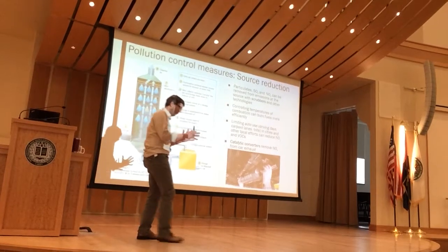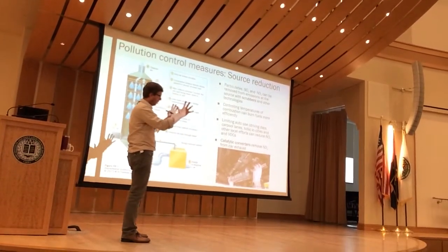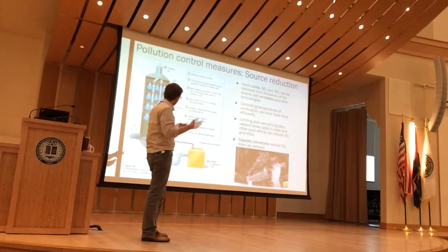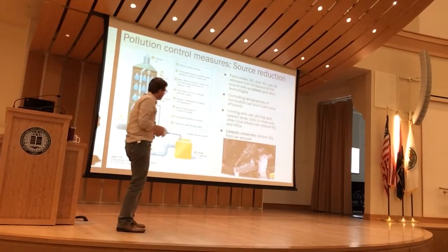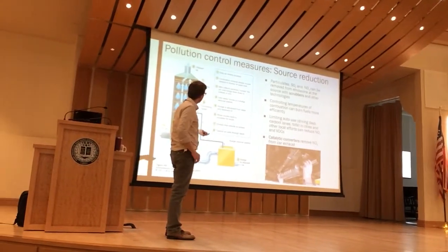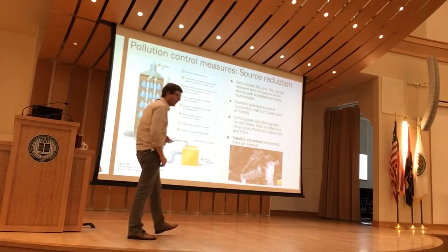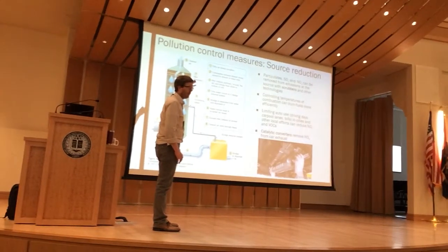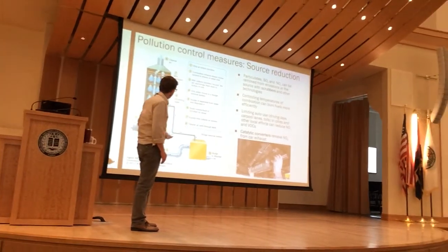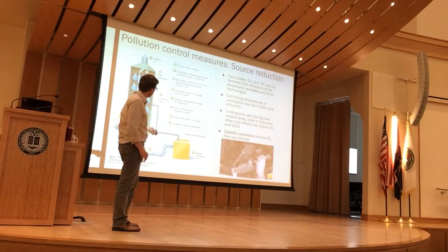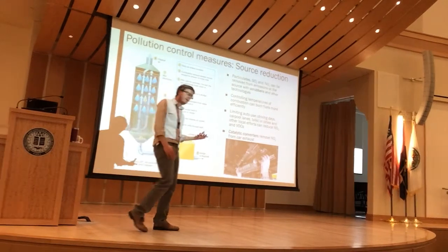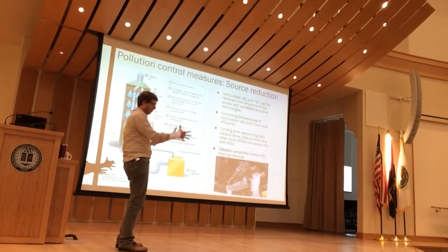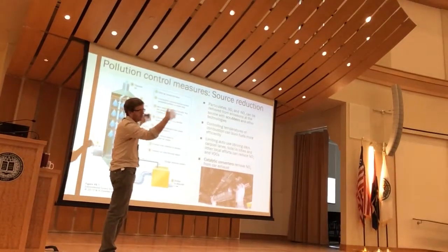In other cases, things like electrostatic filters, which kind of electrically attract particulate. Different technologies exist to accomplish similar things. But this scrubber technology is kind of the classic example. And so we prevent it from ever leaving the factory or from leaving the power plant. That's the idea. Okay. You end up with, much like we've seen before, a waste product that needs to be disposed of. But at least it's a waste product that's right here that I have control over. It's not a waste product up there going wherever the wind goes.